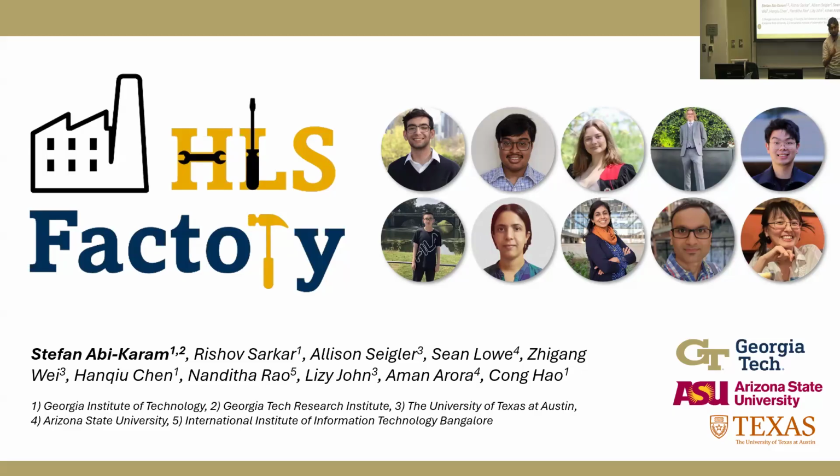The one thing you don't actually have to resynthesize that you can change and get new results from LightningSim is the FIFO depths. In HLS, you can have these things called streams, which are FIFOs. You can write to them and then read from them separately, and you can put them in dataflow processes. You have to size these correctly, and doing that is not trivial.